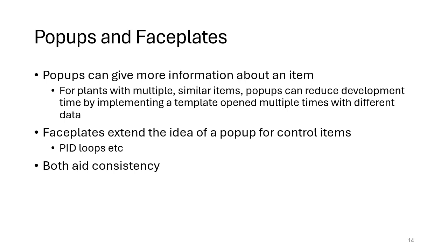One thing you need to think about there is if you're using a pop-up or faceplate, think about the modality of control. If you have an option of a pop-up or a faceplate where it takes focus, then you might force the user just to have one pop-up or faceplate at a time, and they have to close that before they can go back to the main screen. But you might also have an arrangement where you could open multiple pop-ups and faceplates, but then you need to be careful: can your system cope with multiple faceplates or pop-ups? Will the operator get confused as to which has focus? And also you can end up with faceplates getting stuck. So you need to think carefully about how you are going to allow multiple pop-ups and faceplates to be displayed, or are you going to say I'm just going to have one pop-up and faceplate only?